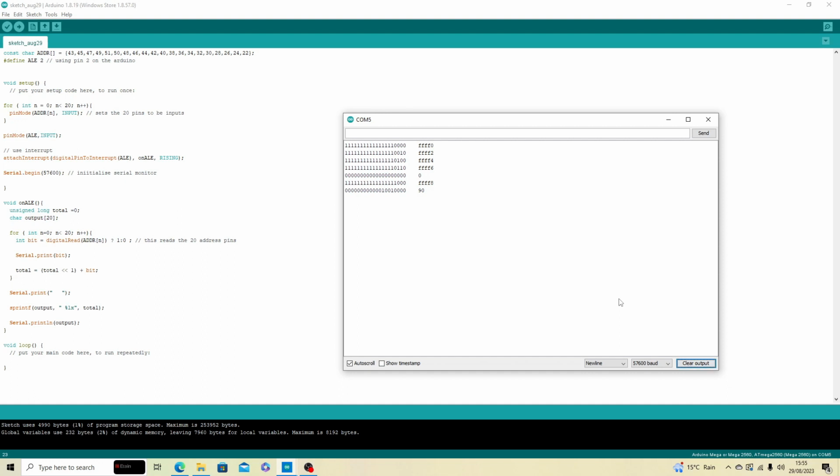So we can actually see the address is going just as it says on the reset from the datasheet. FFFF0, FFFF2, FFFF4, FFFF6, FFFF8, FFFFA. So the data sheet says, following a reset, the 8086 operates normally, beginning instructions at FFFF0, and then we can see it increments forward from 0 to 2 to 4 to 6, etc.